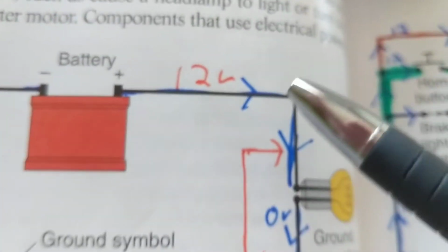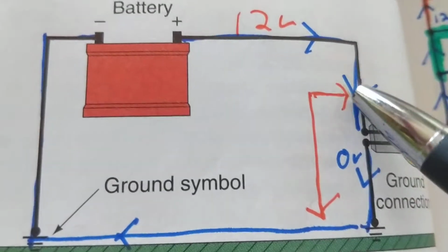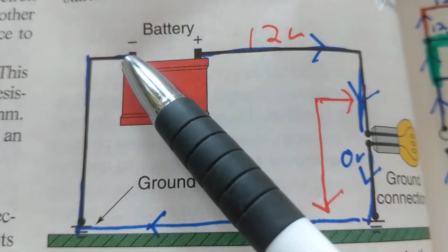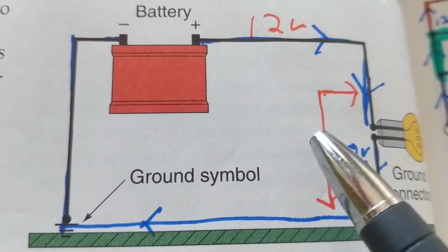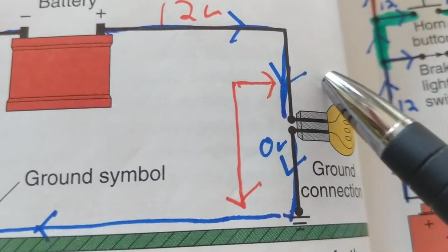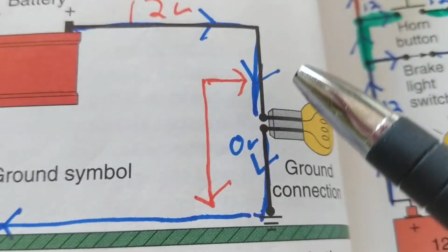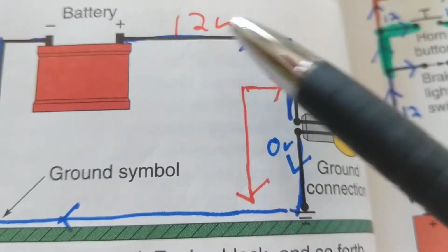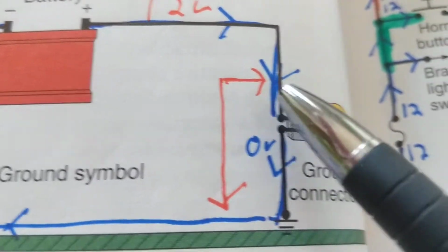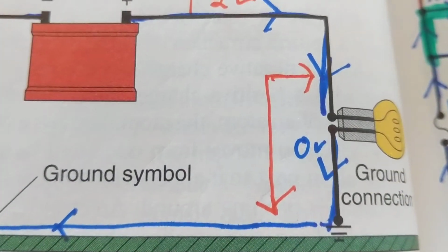Now, obviously, in this simple circuit, there is no fuse. So when we put this jumper across this, we're actually jumping across the battery from positive to minus, and obviously that's not a good situation. That's why you need fuse protection. How much will be on the bulb? 12 volts here, 0 volts over here, because the other side goes to ground. How much did I lose across the bulb itself? If you have 12 volts here, you have 0 volts. I lost 12 volts across this. Now keep this in mind, this is a short to ground. So all the current flows through a short to ground.